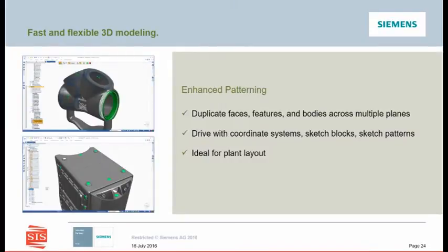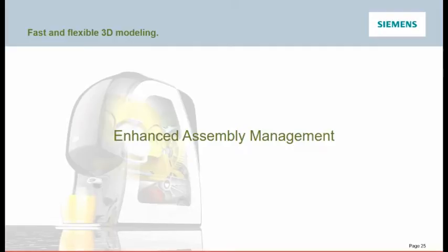In summary, the power of the duplicate tool has grown beyond patterning parts and assemblies. We can now pattern faces and features and bodies using coordinate systems, blocks and sketch-driven patterns, and of course, the beauty of duplicate is that we're not limited to a single plane.